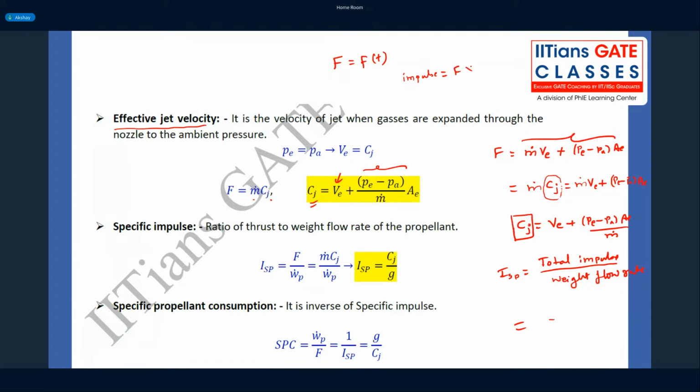That is force acting for a short duration, right? So if you want to get the total impulse, then you have to integrate that function of time over the time period of the rocket operating. Divided by, again we can have a mass flow rate that can be a function of time, dt times g naught. So this is the usual definition of specific impulse, a precise definition, but with certain assumptions.